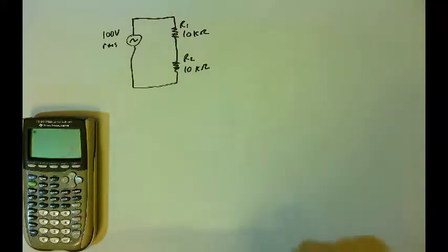And so as long as we use the RMS value for voltage and current, we can solve these purely resistive circuits much the same way we would a DC circuit. Ohm's law still holds true, and Kirchhoff's voltage and current laws still hold true as well. And so we already have the RMS voltage. We're going to go through the same procedure we would for a simple DC circuit.